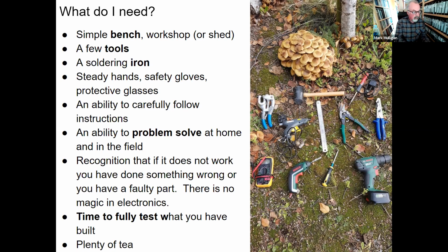It's just a case of using an electronic kit such as a multimeter here to check that the electricity is getting where it should be and the voltages are about right, and take components out one by one, and when your station starts working, you know which component was the problematic one.